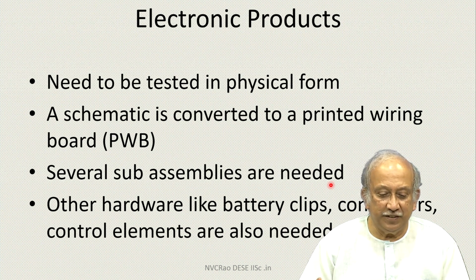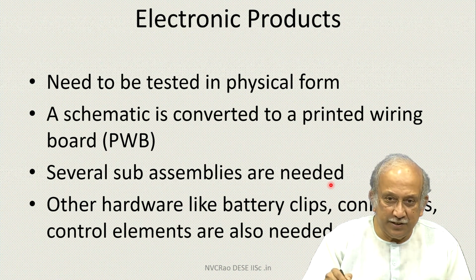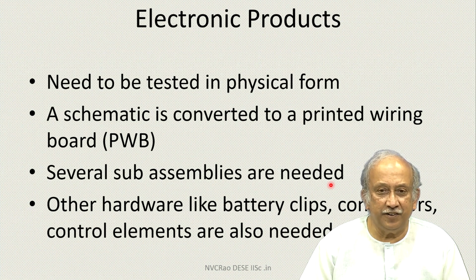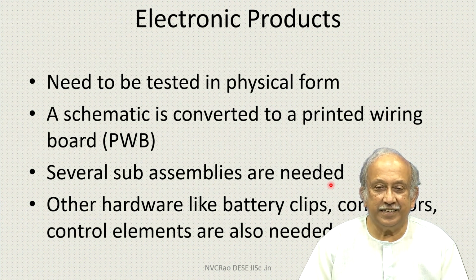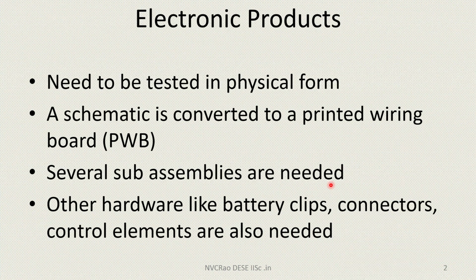Now comes that thing. So, what will you do with the power supply? Do you take it out of that unit you want to build, or would you like to incorporate it into the unit itself? The latest fashion is to try to use a battery, charge a battery, and the battery can be a single cell or multiple cells. By default, with the usual lithium ion, lithium polymer, nickel metal hydride, most of them already come with 3.7 volts, which has become a standard. So, everything finally needs to be split into sub assemblies.